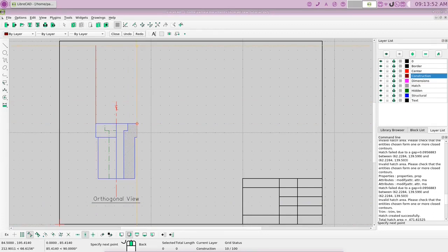and click. Okay, we need to extend a few more of these lines. Let's take the vertical restraint off, click to get rid of that. Make sure snap on end is on, snap on this one, restrain the vertical, go up near the top, snap again. Click to get rid of the tool.